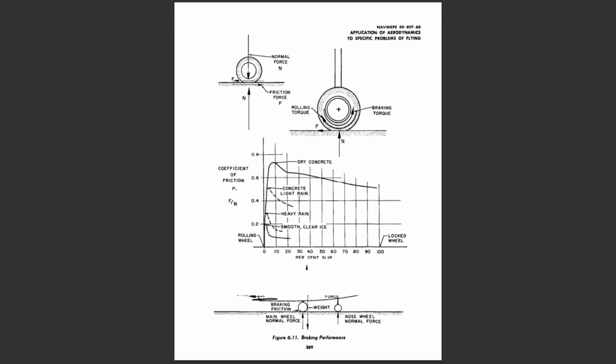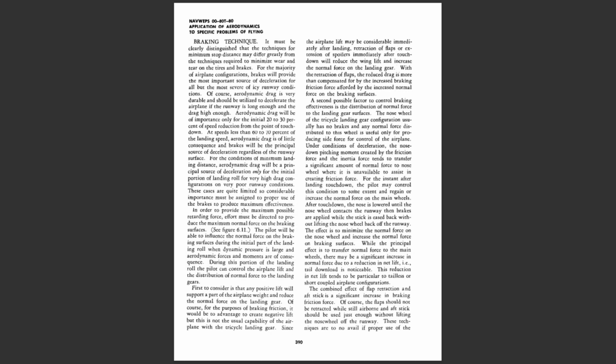In addition, at high rolling velocities on the dry surface runway, the immediate problem of a skidding tire is not necessarily the loss of retarding force, but the imminence of tire failure. The pilot must ensure that the application of brakes does not produce some excessive braking torque which is greater than the maximum rolling torque, and particular care must be taken when the runway conditions produce low values of friction coefficient, and when the normal force on the braking surfaces is small. When it is difficult to perceive or distinguish a skidding condition, the value of an anti-skid or automatic braking system will be appreciated.